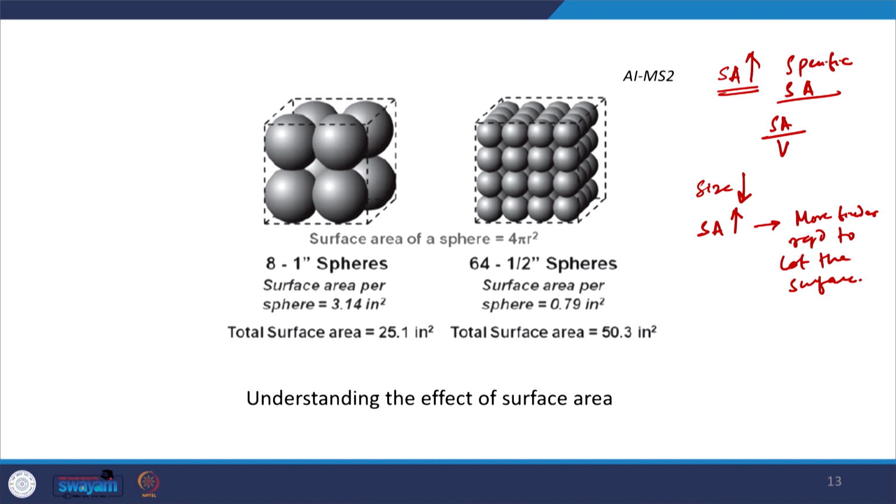And as you know, in the mix usually the air void criteria is fixed, which means that the VMA should increase to accommodate this higher binder content. So in dense graded mixture with lower nominal maximum aggregate size, the requirement of minimum VMA should be higher. Why should it be higher? Because in that mix we will have aggregates with smaller sizes, which means more surface area, which means that more binder will be required to appropriately coat these smaller size aggregates.